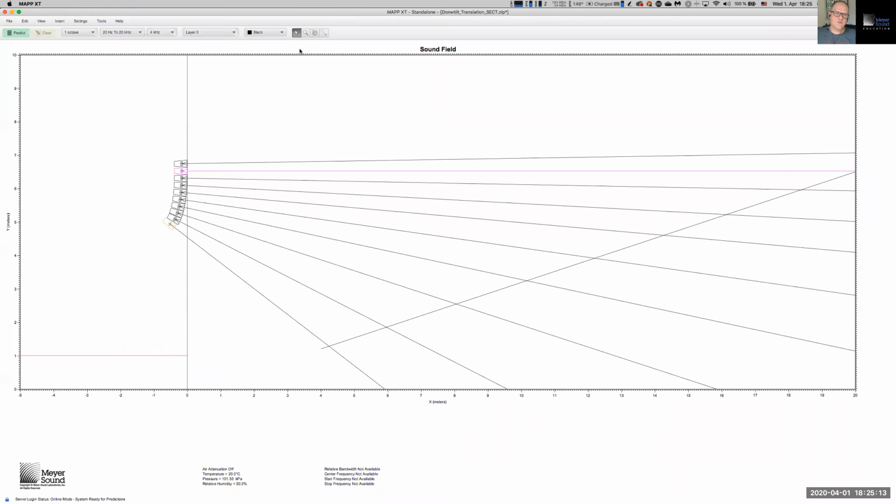And now I'm going to use a different attempt. I go to the architectural 8, and I'm going to draw a line segment starting at where the loudspeaker touches down on the first row. There's my line segment, and I'm going to connect the speaker to the first row. I'm now going to select the line segment, which is the distance between the loudspeaker and vertical bottom where coverage is supposed to start. I'm going to select the rotate tool.